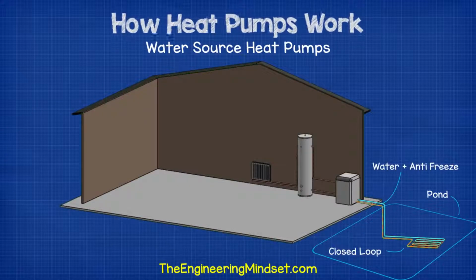In a closed loop type, a water and antifreeze mixture cycles around the pipes to collect the thermal energy and bring this to the heat exchanger, where the refrigeration system will then absorb the energy and use it for heating. Alternatively, it will dump the building's unwanted heat into the water antifreeze mixture to provide cooling for the building. The unit then works the same as a ground source heat pump.